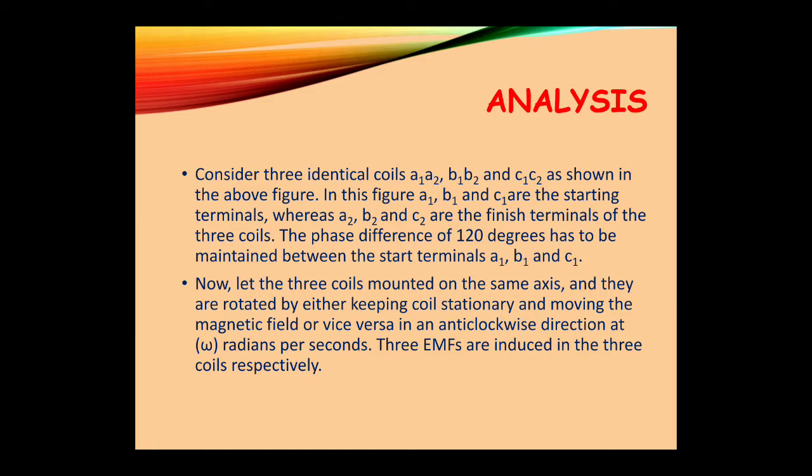Now let the three coils be mounted on the same axis, and they are rotated, either by keeping the coils stationary and moving the magnetic field, or vice versa, in an anticlockwise direction at omega radians per second. Three EMFs are induced in the three coils respectively, and the electrical angle between the three EMFs is 120 degrees.